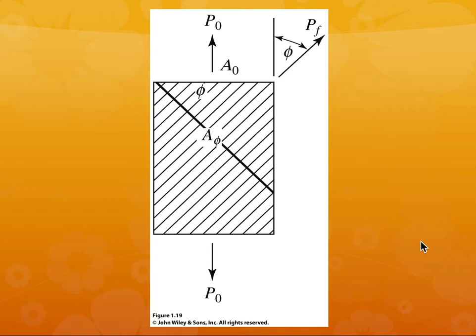And if they are not entirely aligned to the normal loading direction, you can actually calculate the values of the properties of the composite in different directions and combine all of them together in order to get the elastic modulus of the composite itself.